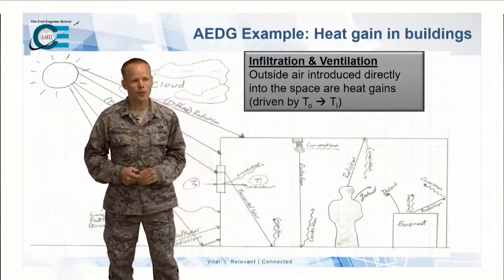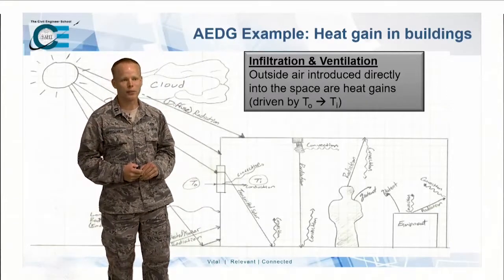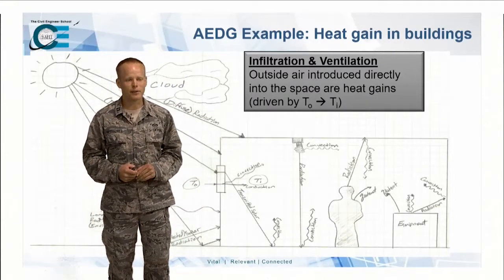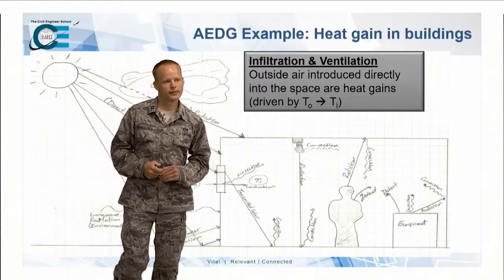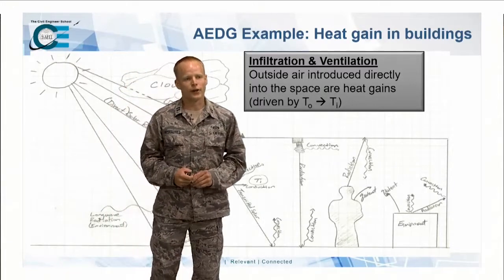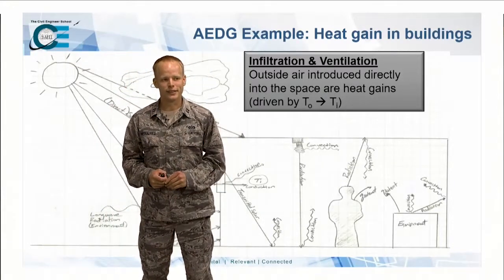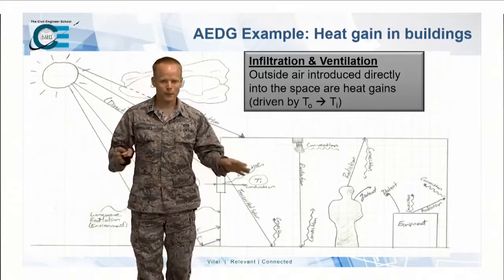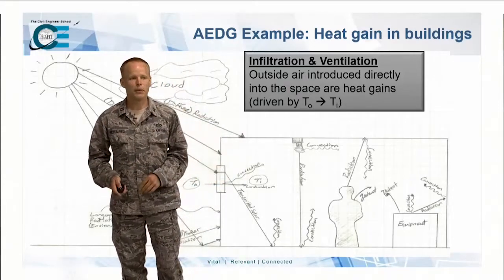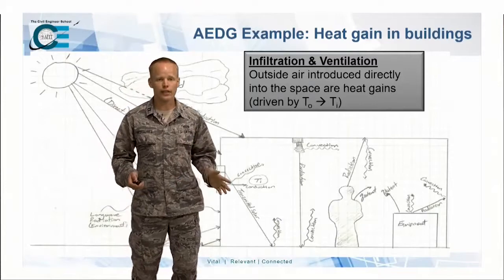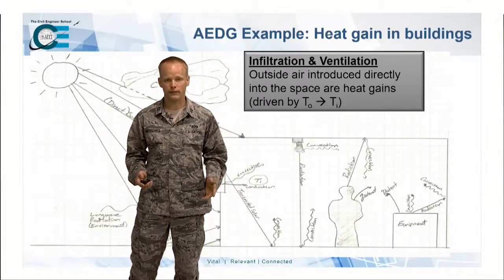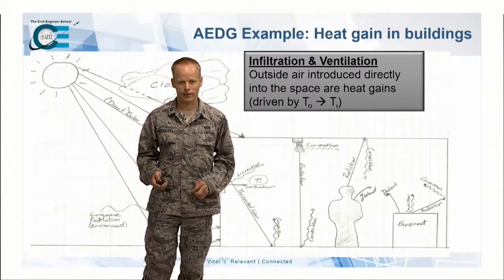Exactly. Install better glazing with reflective coatings, plant trees to help shade. Man, you are beating me on this lecture. So you're reading ahead on the slides, or you already know this. Either way, we're covering it. But yeah, exactly that. Those are things that you will have to do to optimize your building. But you'll have to do this based on your site.